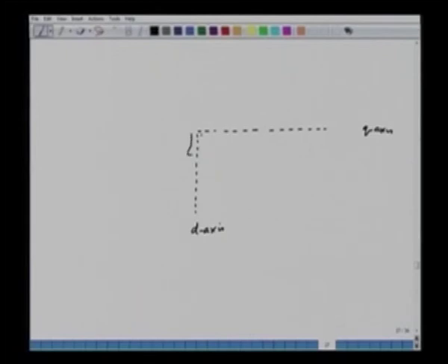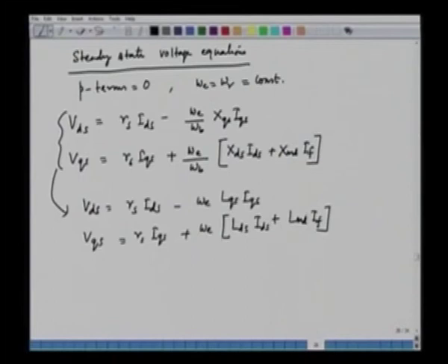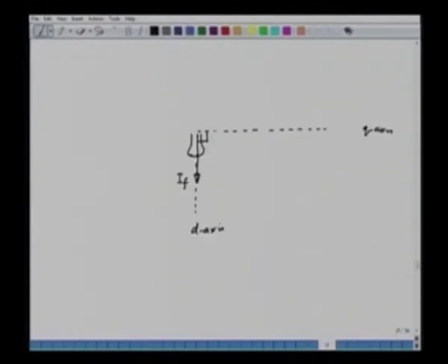We have the field in the d axis, the field pole, and the field current IF is in the d axis. We can show that to be IF here, this is a right angle. And then what we will do here, we will first write down the q axis induced EMFs. We have this term LMD IF into omega E. LMD IF into omega E is the same as the field induced EMF, so we can say it is the same as EF.